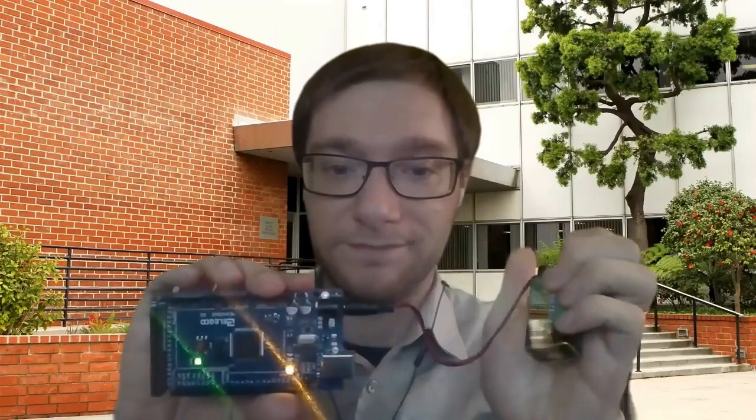You can also power the actual Arduino with this as well, like that. See? Or more likely, you'll power your Arduino with the USB plug. This will go into the silvery metal part, and then the Arduino board will get both power from your computer through this USB cable, and it will establish communication with your computer too. That'll come in handy next week more than this week.